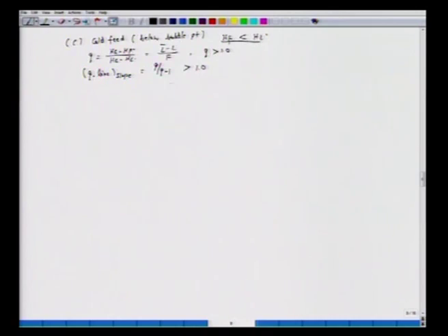So if we plot, let's say this is the 45-degree line, this is XD, here this is XF, and we have XW. The slope of the q line is greater than 1, so it will be something like this. We have one operating line and the second operating line which will intersect like this. So this is your q line. You can write, this is your 45-degree line on your graph paper.